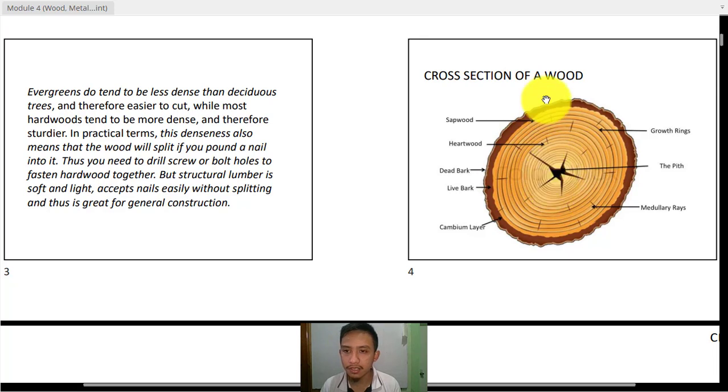They are actually sawing or dividing this cross section, and they will try to remove the pith, since that pith is what we call the juvenile wood. It's juvenile, that is still very weak. So we avoid that. Most of the time we are getting the outer part or the outer growth rings if we are trying to cut a lumber.